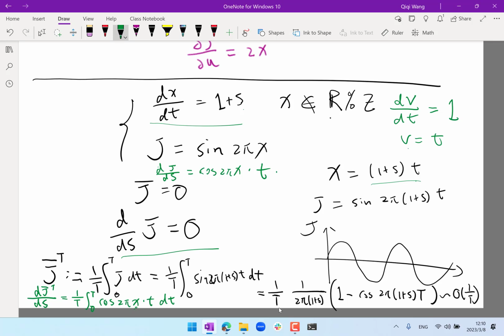Then the only prediction you can make for the system is the statistical quantities, right? For example, if you are looking at a nuclear reactor or an airplane, the smallest turbulent scales are usually in milliseconds or even microseconds. And the only thing you hope to predict is the long time averaged, for example, heat transfer rate or drag on the airplane. This is something you want to optimize and design, and therefore you want to take the derivative of the quantity of interest averaged over a long time with respect to a certain control parameter or design parameter of the system. And that's the d J bar d s we are interested in, right?